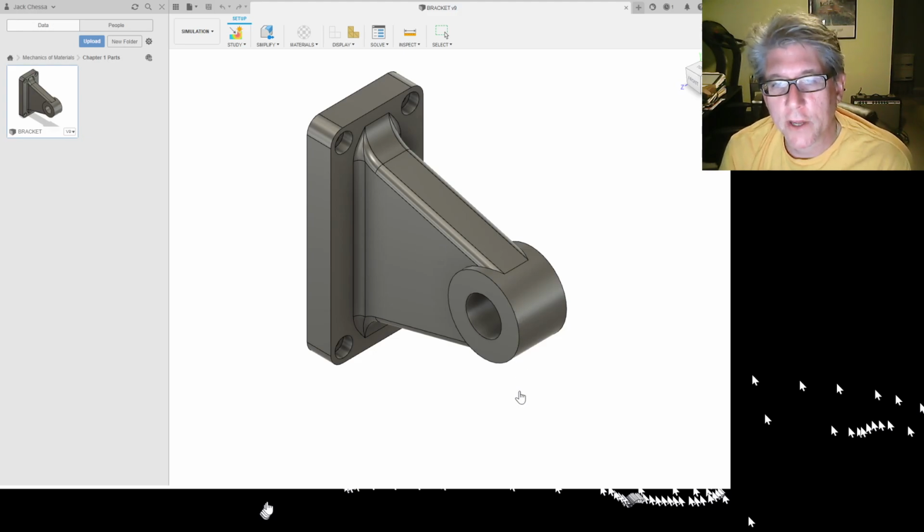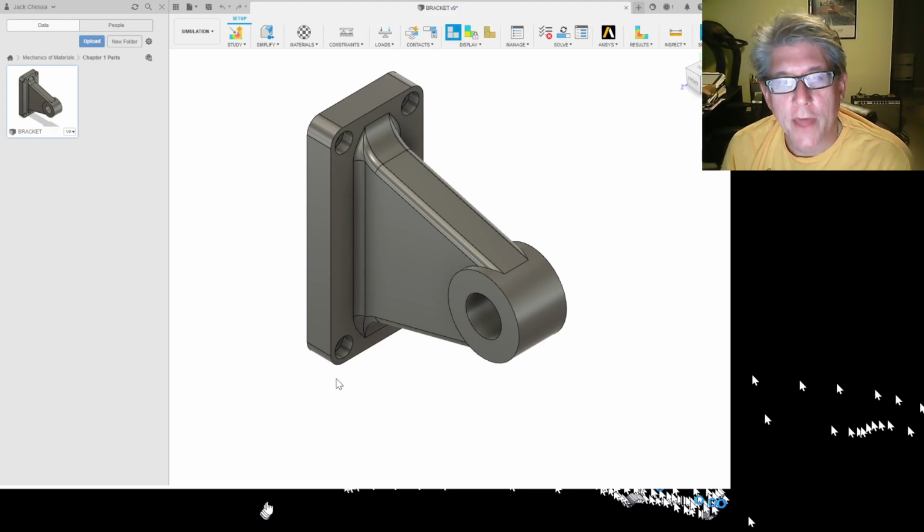Fusion's actually getting quite good at doing some reasonably sophisticated modeling, and so I encourage you all to take a look at it. But we will just be using static stress analysis in this class. So okay, fine. Click on create study, and that will create, you can see down here on this tree, study 1, static stress, and you can see it has materials, and then load cases. We'll have one load case, and in the load case you have the mesh as well as the boundary conditions, which are the loads and constraints. Okay, and we'll go through all those.